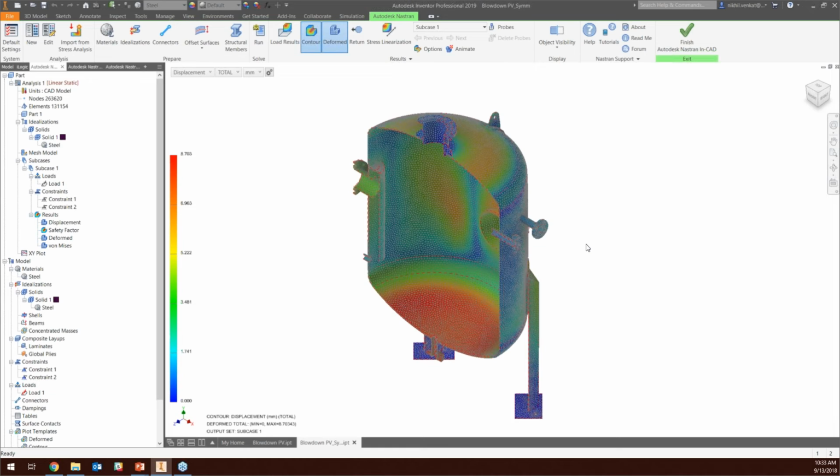You just want to make sure that you're moving in the right direction in regards to your design, not necessarily saying, hey, I'm going to run into 0.726 millimeters of displacement at this point, and that's exactly correct. Remember, it's not going to be completely the same. When you're looking at materials as a whole, when you're looking at a lot of these alloys, it's probably not uniform. The material properties of the particular steel you're using aren't going to be exact across the entire width of the section. So just a couple of things to note there.